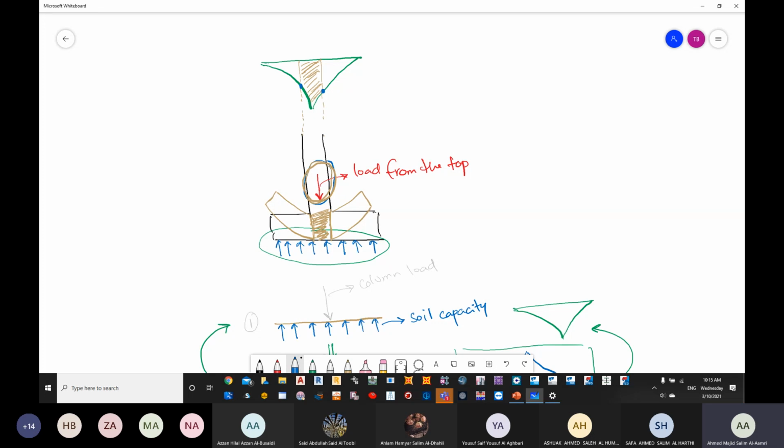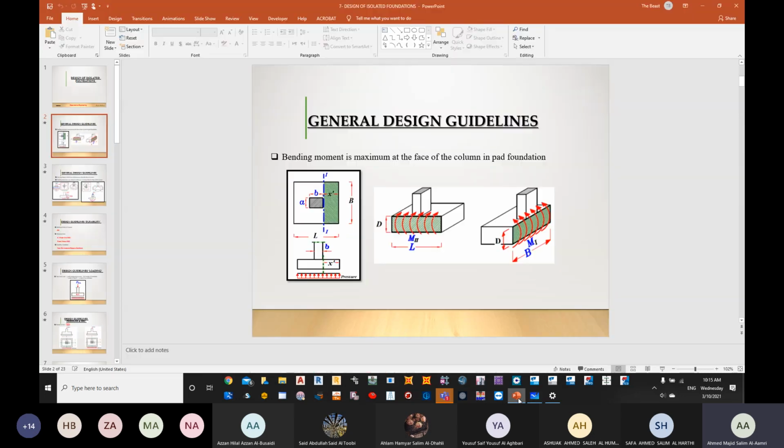And once again, you can try it with your bottle of water or the pen. The position or location of your element is not going to be bent up. The other areas are going to be bent up. So what we understood is that the maximum bending moment will be occurring here and here. Now, where are these two locations? These locations are representing what we have mentioned in our guidelines, by saying that the bending moment is maximum at the face of the column.